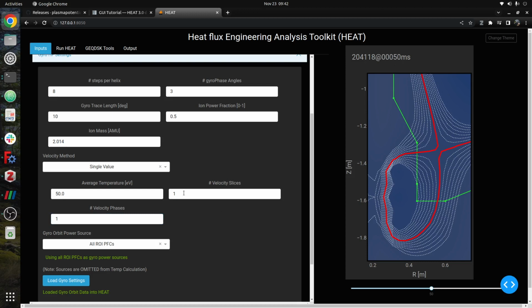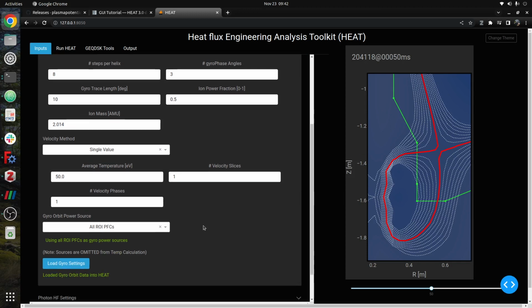But usually I would say you want to start with something like 3, 3, 3. And I've run up to like 12, 12, 12, 15, 15, 15 before. It can be computationally expensive, so it can take on the order of hours, maybe into days if you have a super big mesh. So start with something small and then see how long it takes. Make sure that your inputs are set up and then run it overnight or something.